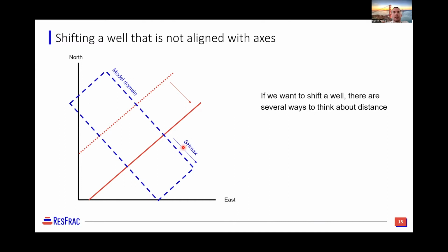Our convention is to set up the model such that our matrix region, as shown by this dotted blue box, is along the azimuth of SHmax. The reason we do that is that fractures then grow parallel and perpendicular to the meshing, which is efficient from a computational perspective, and also from using the imaging in the tool or visualization, it makes things much cleaner.